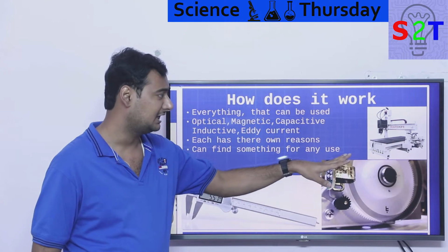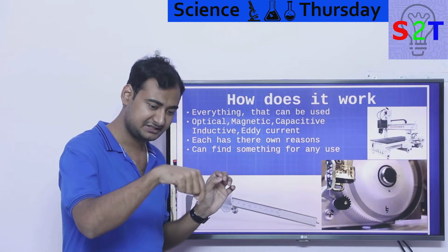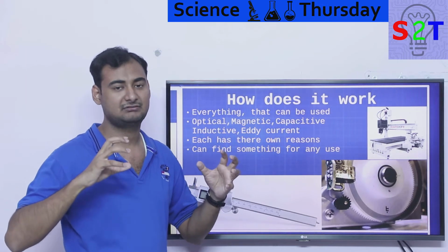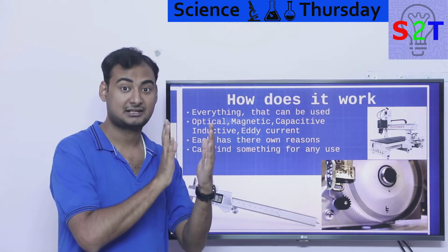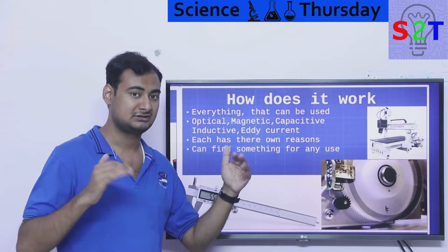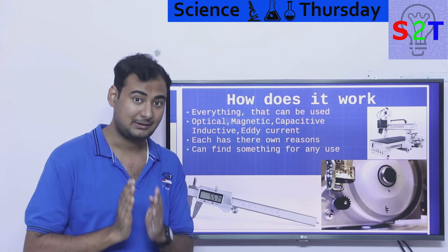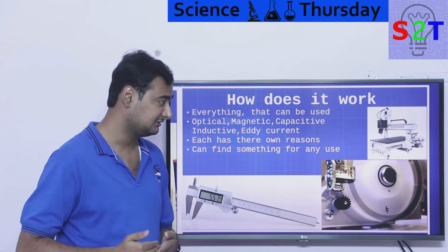However, if you go to a very high-end one, it will have encoders in the linear rail itself. If it receives a command, because there is always a bit of lag between your nut and bolt and the carriages, they always have a bit of flex, so to say. So encoders in the linear rail itself add to your cost and software complexity, but they do give you absolute feedback, hey, you have drifted. So you can understand there is always a need for that.